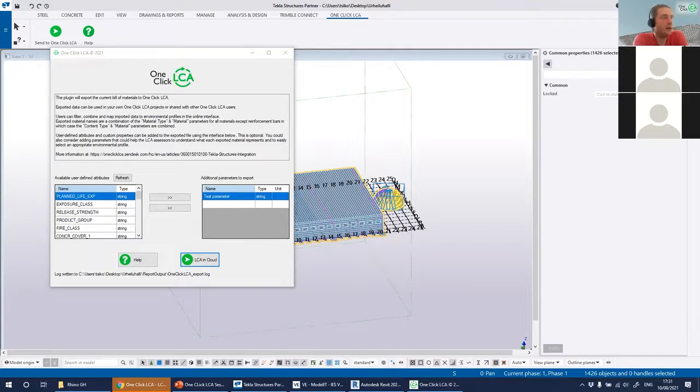Another thing that I would suggest is, once you think you've done as much as you could in the LCA in Revit, or in Rhino or Grasshopper or any other plugin, you can send them to one-click LCA, to the cloud application, and basically download the Excel and do some further analysis in Excel if that is required. That would probably be relevant for quite big models that are quite inaccurate, where the material names are not very helpful. So I would suggest that as well.